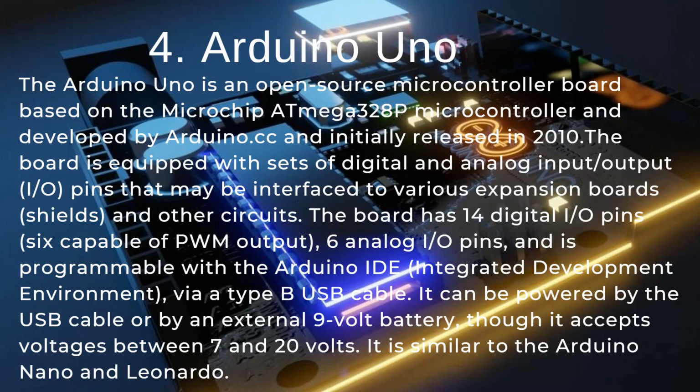The Arduino board has 14 digital pins and 6 analog pins, so that we can interface our external peripherals to the digital pins which are given, and the 6 analog pins. There are also PWM pins, which are marked with a tilde symbol.